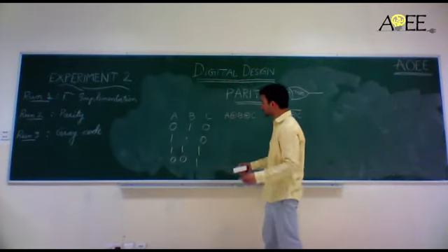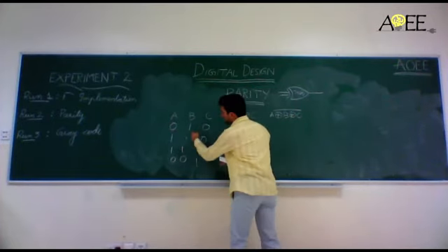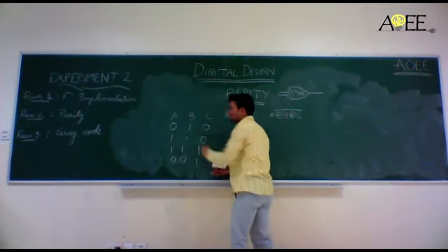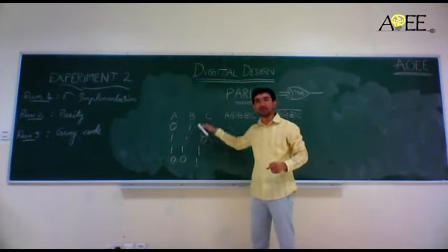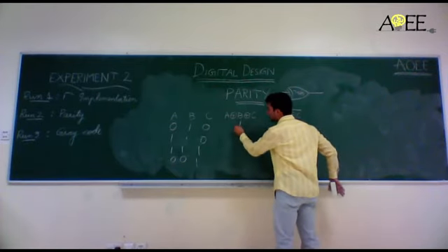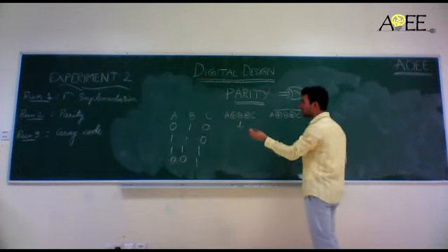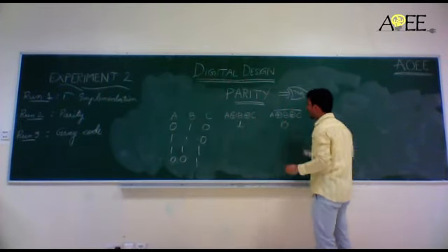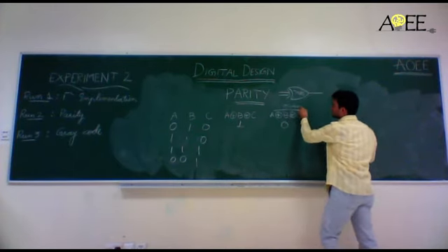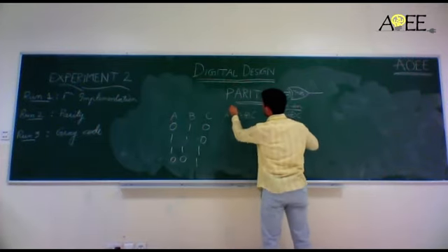So we have 2-3 combinations over here. Over here, as is visible, there are 3 inputs and only one input is high. B1 is odd, so an odd number of inputs are high, so the output is 1. And here, even if the number of inputs high is an odd number, the output is low. For even parity, this is odd parity. Odd parity.